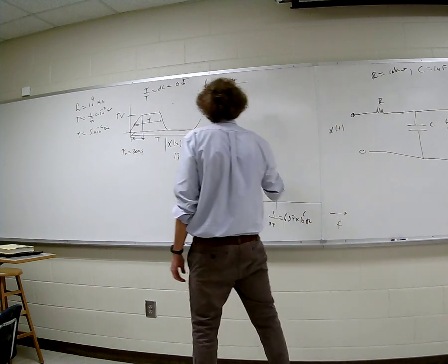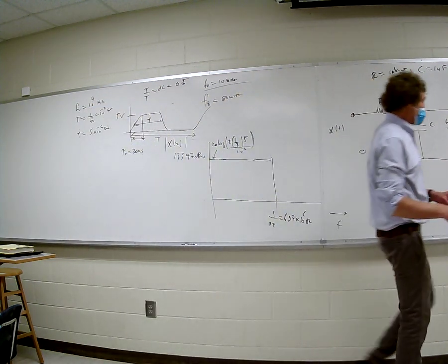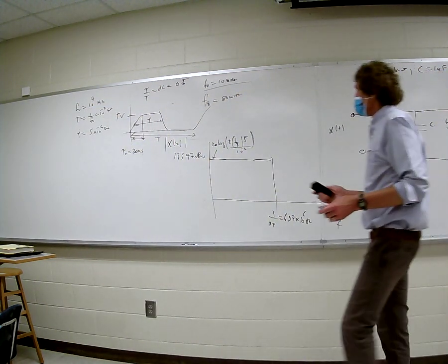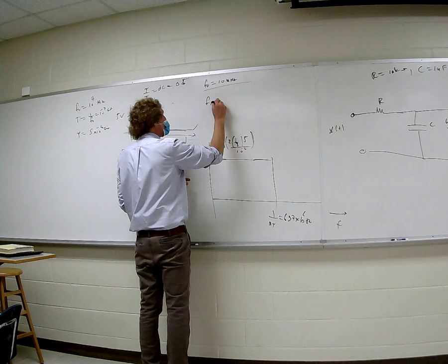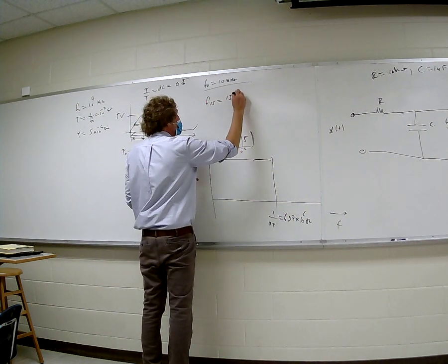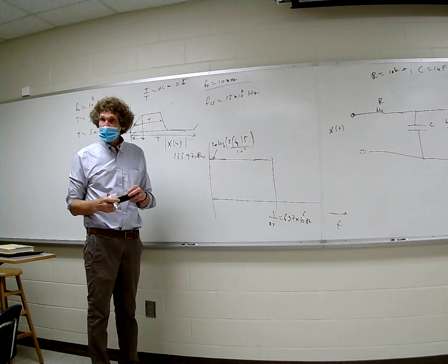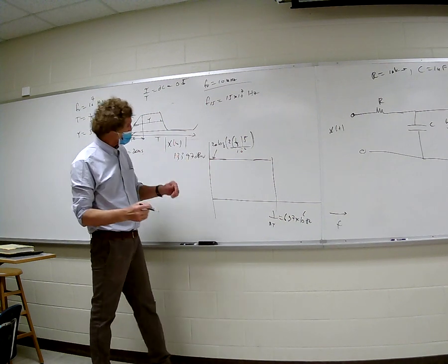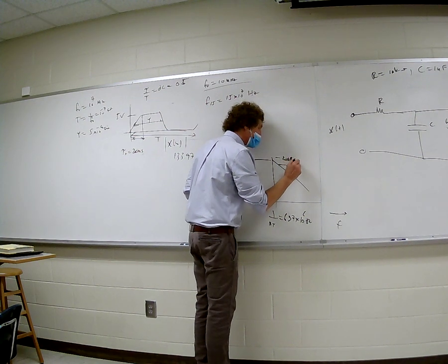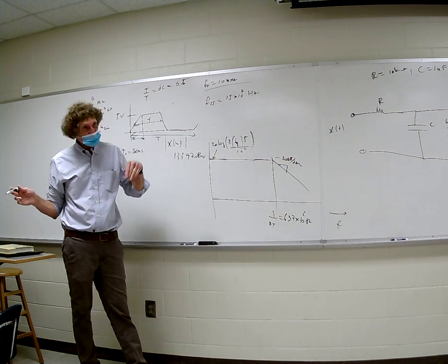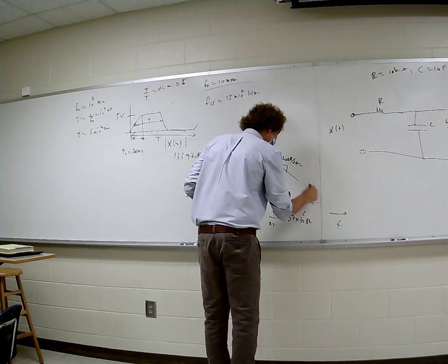All right, matter of fact, let's not do the 8th harmonic. Let's do the 15th harmonic. I just decided to go up. So we're going to say F15, which is going to be 15 times 10 to the 7th hertz. It's 150 megahertz. You with me? All right. Now, at that point, the input signal starts coming down at minus 20 dB per decade, right? It's going to keep going down until 1 over pi times tau rise. Right, until this point, right here.